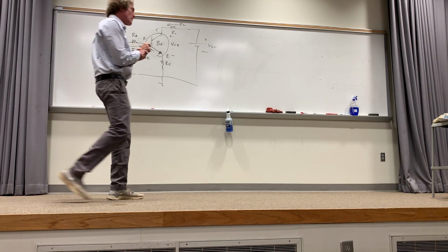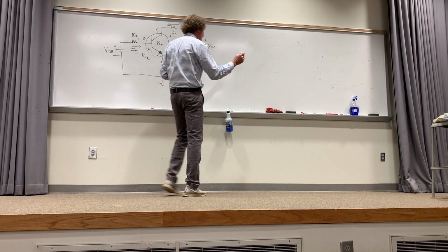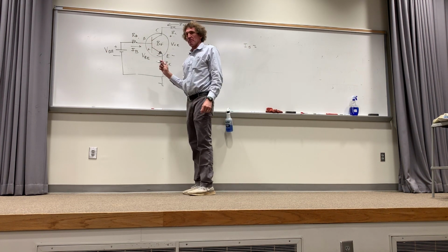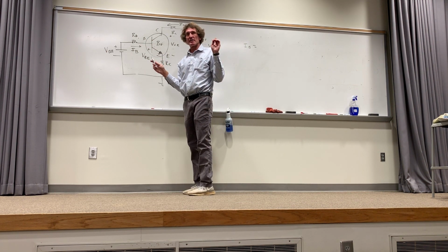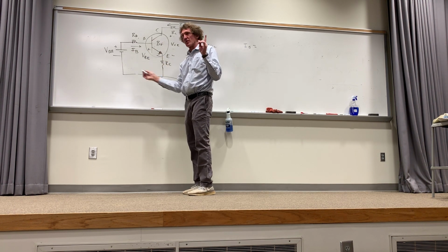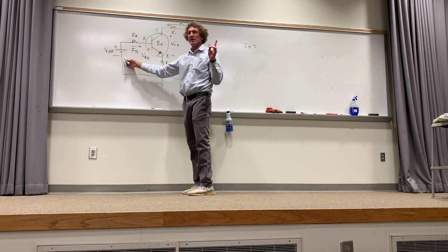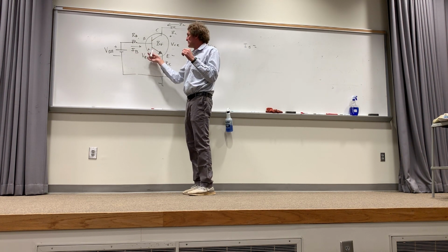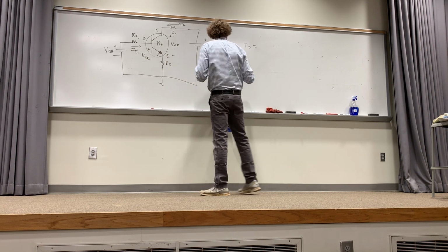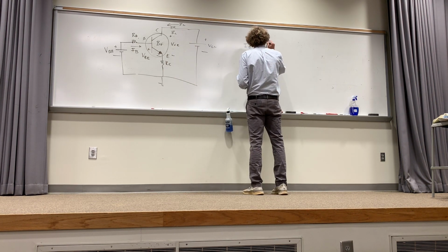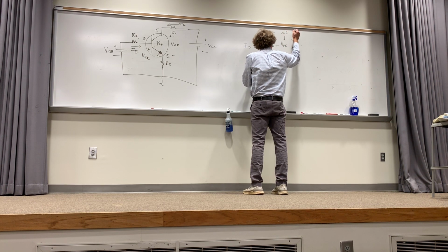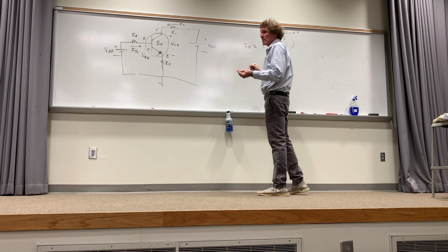All right. Now, first, you got to get the base current, and I'm going to explain this. Last time, I wrote a loop equation here, right? But ultimately, I knew one thing, that the net voltage that's driving current this way is caused by VB. You all agree? So it's that voltage, but I have to subtract the VBE to get the net voltage that's driving current around. So I put VBB minus V base to emitter, whatever that is. That's usually 0.6 to 0.7 volts. For me, it'll be 0.7.